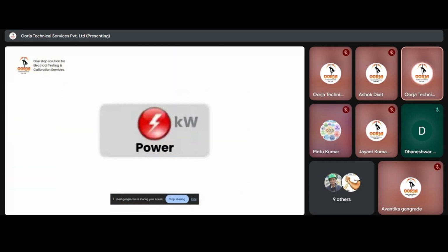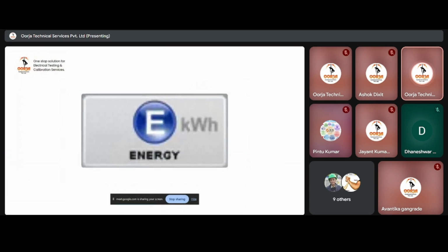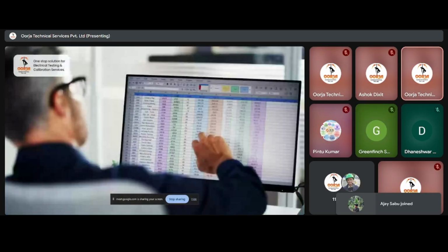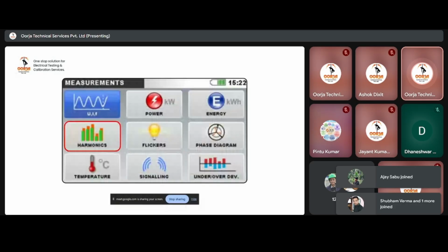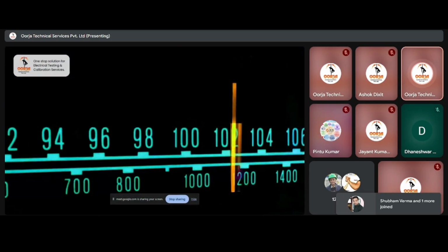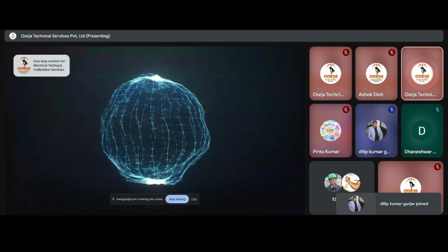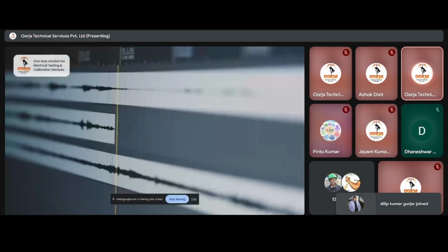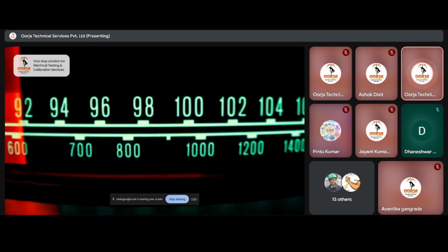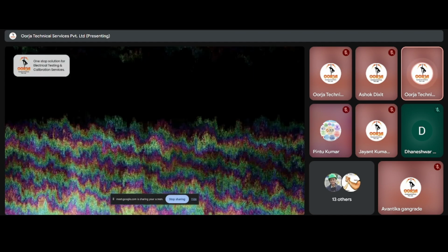Power. In power screens, the instrument shows measured power parameters. Energy. The instrument shows the status of energy counters in a tabular meter form. Harmonics. Harmonics presents voltage and current signals as a sum of sinusoids of power frequency and its integer multiples. If a signal decomposition with Fourier transformation results in the presence of a frequency that is not an integer multiple of the fundamental, this frequency is called an interharmonic frequency, and a component with such frequency is called an interharmonic.